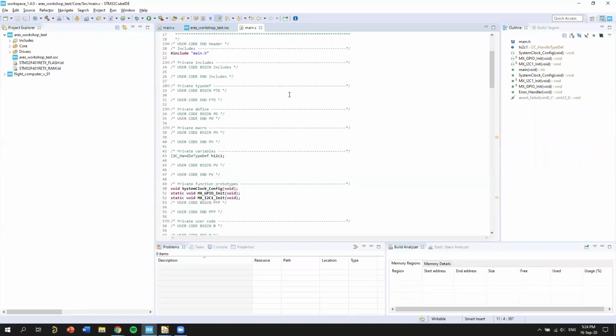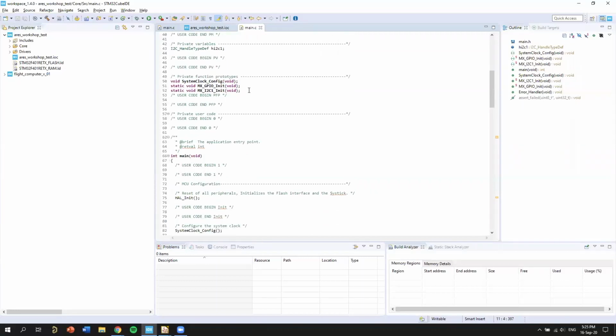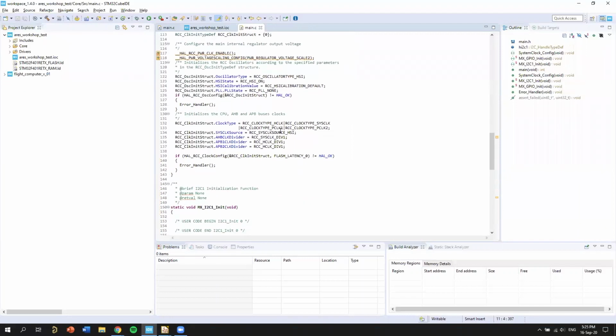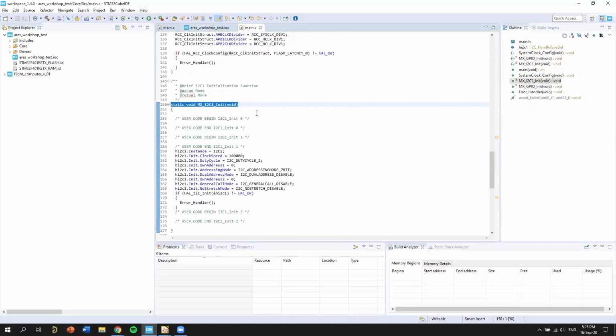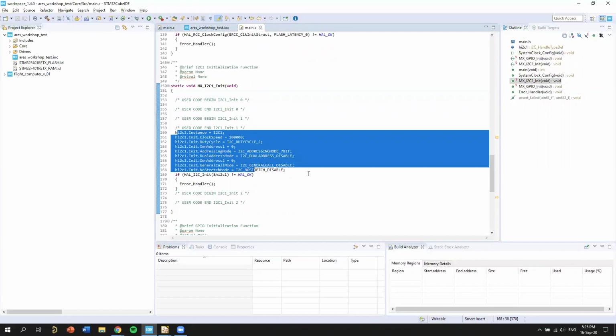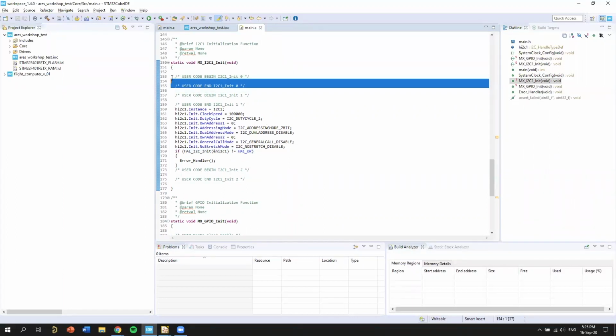Oh yeah, by the way, this is all in C, but it's C with the hardware abstraction library from ST. It's another thing that you have to learn on top of this. But you can see here, now that we enabled I2C, it generated this function, which has all of our I2C initialization code. For the processing where you want to write your own code, it tells you to put your code within these blocks. We have to put it inside those blocks because when it generates the code, it'll overwrite anything outside of those blocks. They're just all around the place.